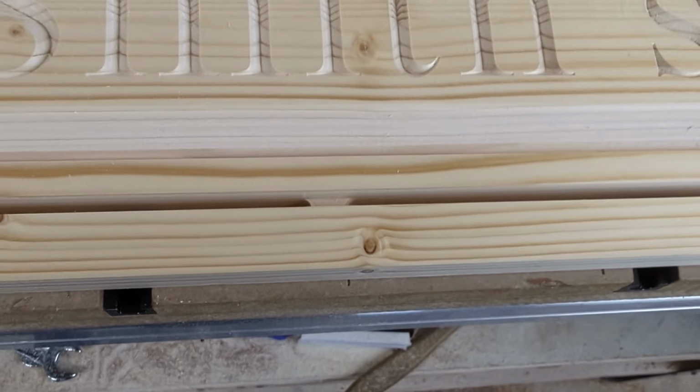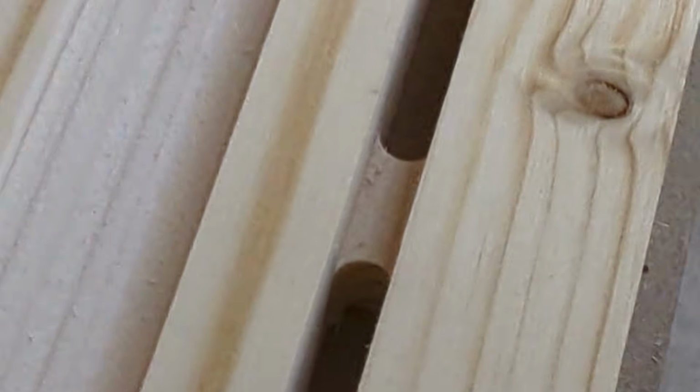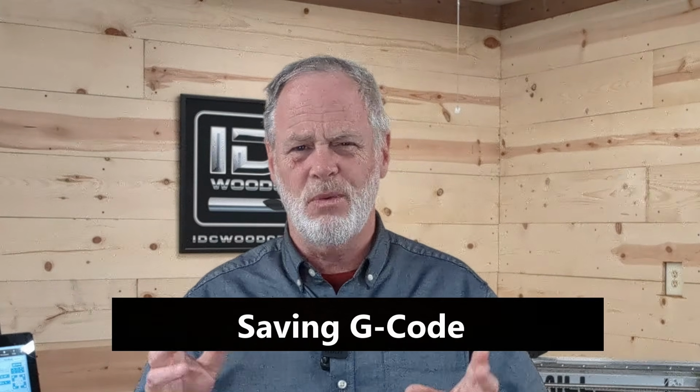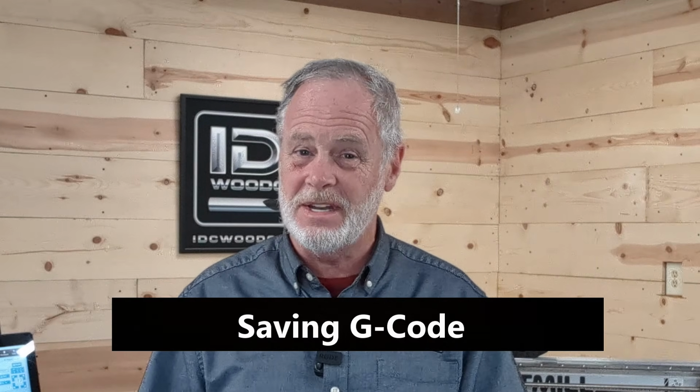Definitely practice that. The next thing we're going to get on is to doing tabs. Tabs are little pieces of wood that attach your finished project to the waste material. You'll want to do that because if you're cutting something out, you don't want it to move at the last minute. So tabs are really important, and then we're going to get onto the final thing, which is toolpaths. So we have another 20-25 minutes to go.